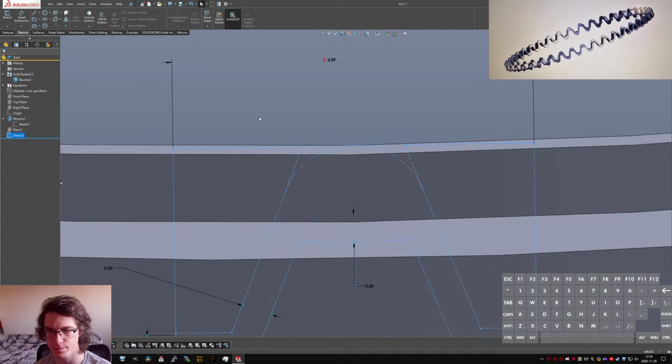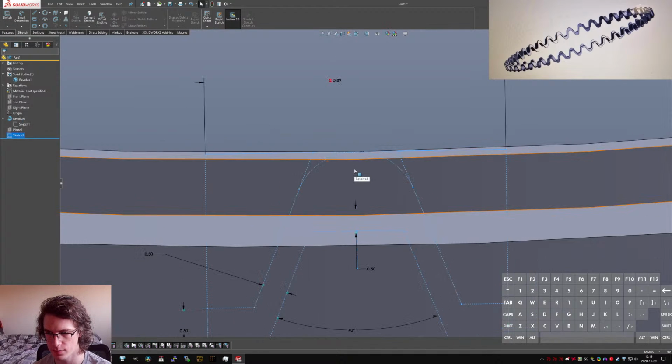So I'm going to forego accuracy here, I think. If I really wanted to, I could extrude this shape with like a boundary extrude and use some radial lines. And then I could use a combined feature and then a circular pattern if I really wanted to get the geometry super accurate. But I don't think it's really necessary because this edge, you're shaving micrograms maybe, I think.